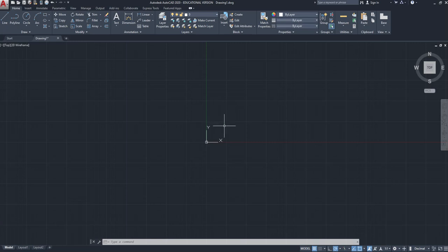We have this grid. When I zoom in, you can kind of see this grid. It's sort of an implied grid. If I wanted to locate my cursor by clicking, it's somewhat hard for me to locate this intersection right here of this grid just by using my mouse. So what I'm going to do today is show you how to access these intersection points just by using a coordinate input. I'm telling you how AutoCAD is organized just so that it makes sense.